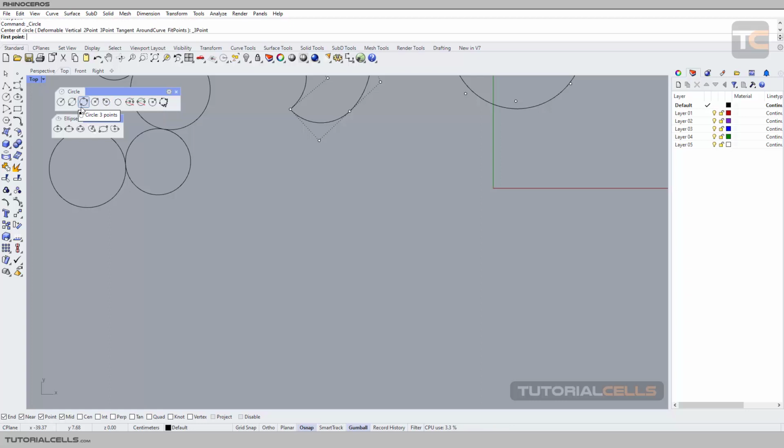For example, you can draw any vertical one in all of this. I explain them here. Here you can draw an ellipse. From the center, click to specify the center, the second for its radius, and then click and drag for the second axis, and you can, for example, type any number that you want there.